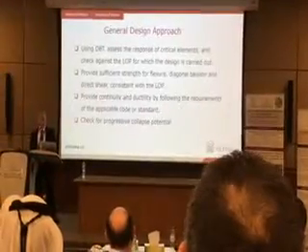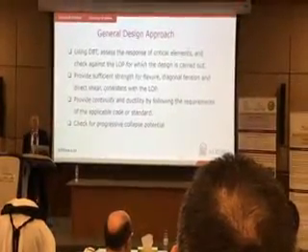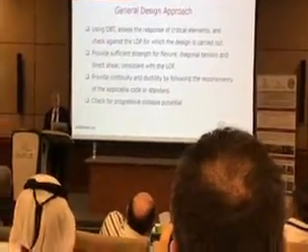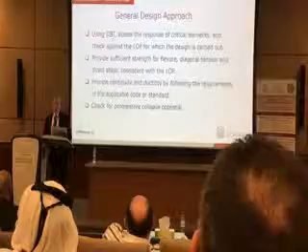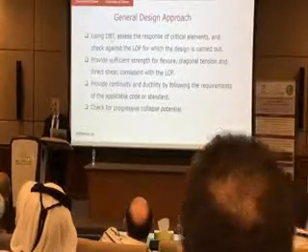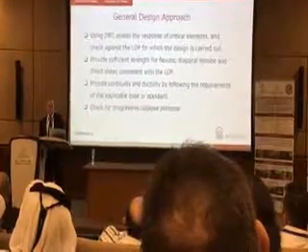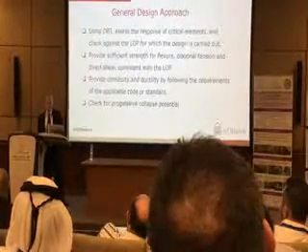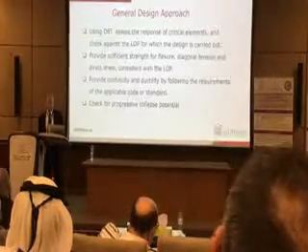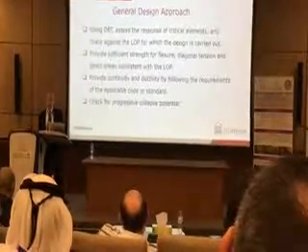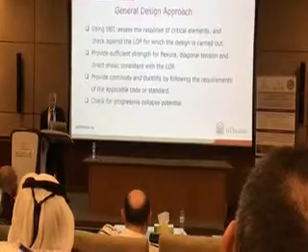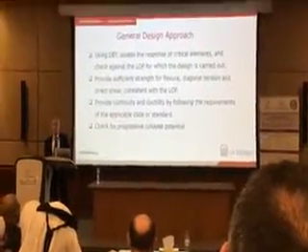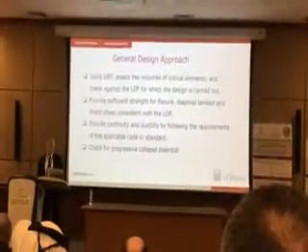Okay, so then we're approaching the end of this design presentation, and general design approach involves you first come up with design basis threat. This is the charge weight and standoff distance, and you decide on level of protection, or the building owner decides on level of protection. You do your analysis to see what is the demand in terms of strength and ductility, and then you provide continuity and deformability to make sure that you meet those target levels.